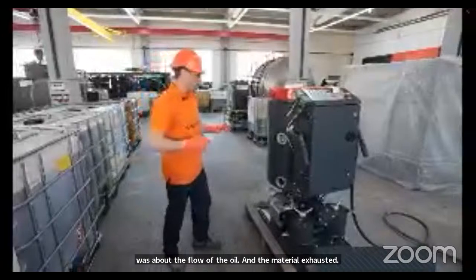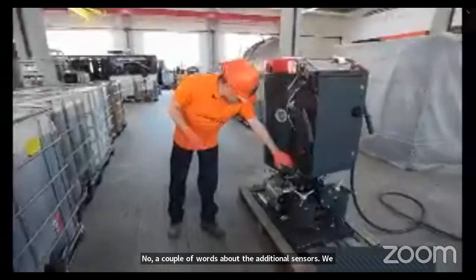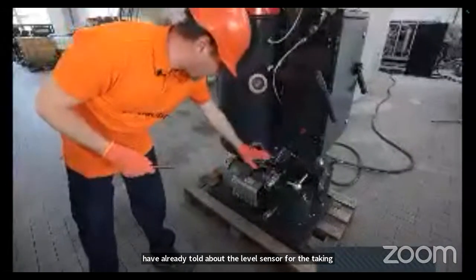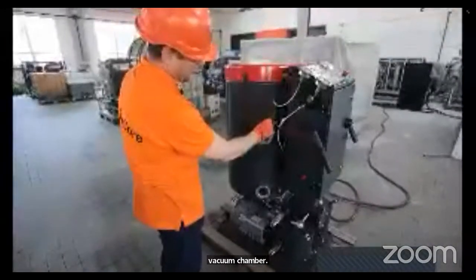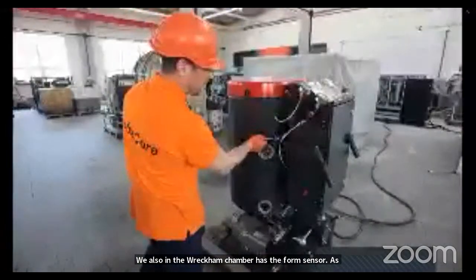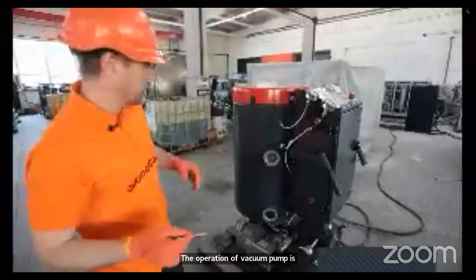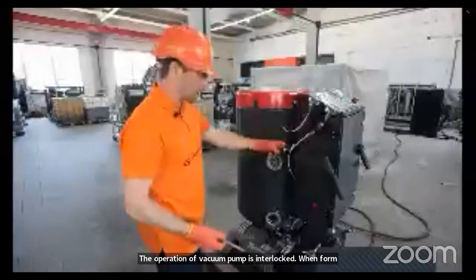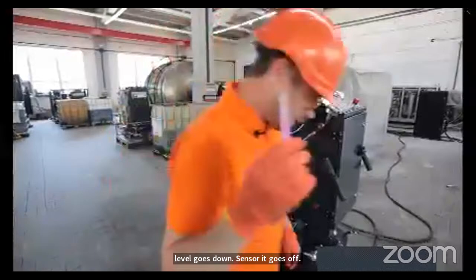Now, a couple of words about the additional sensors. We have already told about the level sensor for detecting oil and maintaining a certain oil level in the vacuum chamber. We also have the foam sensor in the vacuum chamber. As soon as the foam is detected by the sensor, the operation of the vacuum pump is interlocked. When the foam level goes down, the sensor goes off, and the vacuum pump starts automatically.